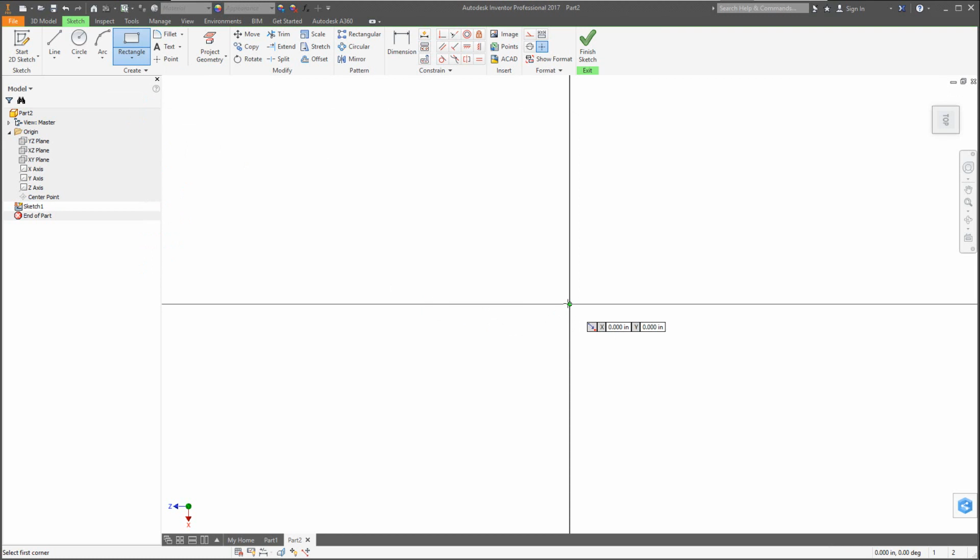And I'm going to glide up to that little point there in space, which is our origin. That's our 0 marker in space for 0, X, Y, and Z currently. And so once it turns green, or again, yours might turn to a different color, click. That means you snap to it. Now as you drag this out, you'll see that there's dimensions. The blue highlighted dimension, you could start plugging away right now.